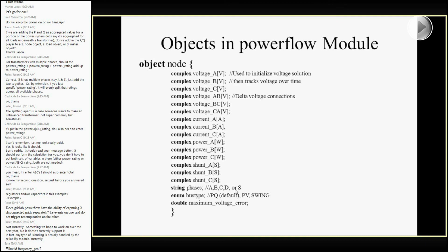The question is, what is the frequency generator? Frequency generator is a highly development stage, experimental, please don't use it, thing that was put into GridLAB-D to do a rough approximation of system frequency. So basically you would attach it to either the head of your feeder or your swing node on your power flow, and based on how the power is changing on the system, it would provide you a rough approximation of how the system frequency is adjusting.